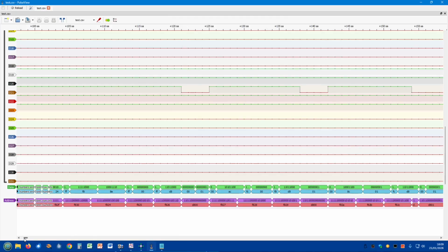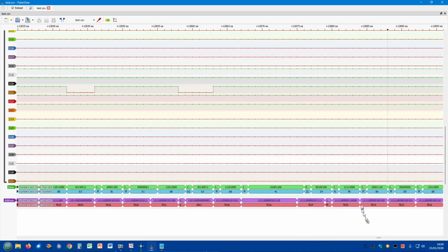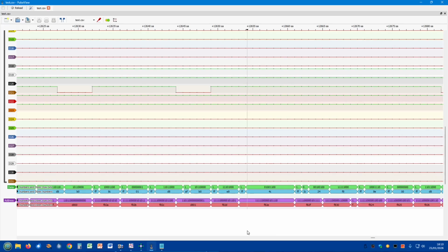We're a bit further up here. Let's see if we get any bigger numbers. Only bit 6 coming on. Oh, what have we got here? That's coming on from RAM, so we're definitely getting it come on. There's an F8. We've got the bits on there. So we know our bits are going on and off okay. That ROM chip's not working properly on the board, which is the bit we can't replace.